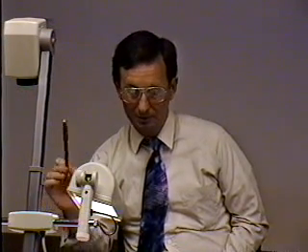We've got a normal depth of 4.8 feet. So if you get far enough away from the river, up the creek, up the concrete channel, so there's no effects, the depth's going to be 4.8 feet. But it's flowing into the river, so the depth's going to be 10 feet in the river. And so you're going from 4.8 feet to 10 feet.